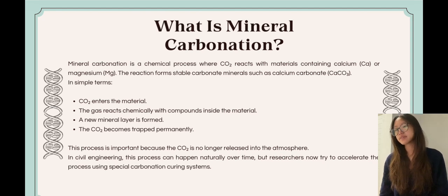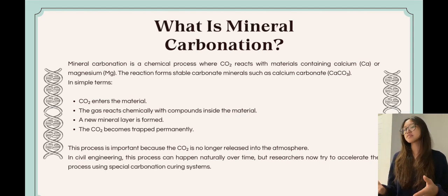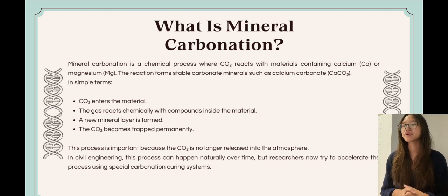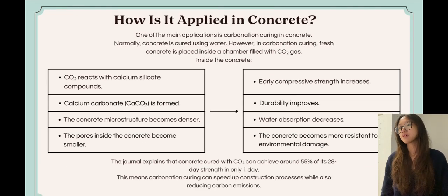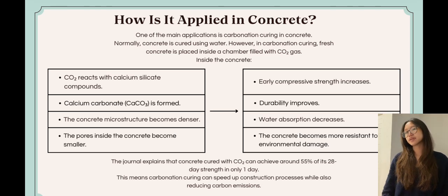In civil engineering, this process can happen naturally over time, but researchers now try to accelerate the process using special carbonation curing systems. So how is it applied in concrete? One of the main applications is carbonation curing in concrete. Normally, concrete is cured using water. However, in carbonation curing, fresh concrete is placed inside a chamber filled with carbon dioxide gas.